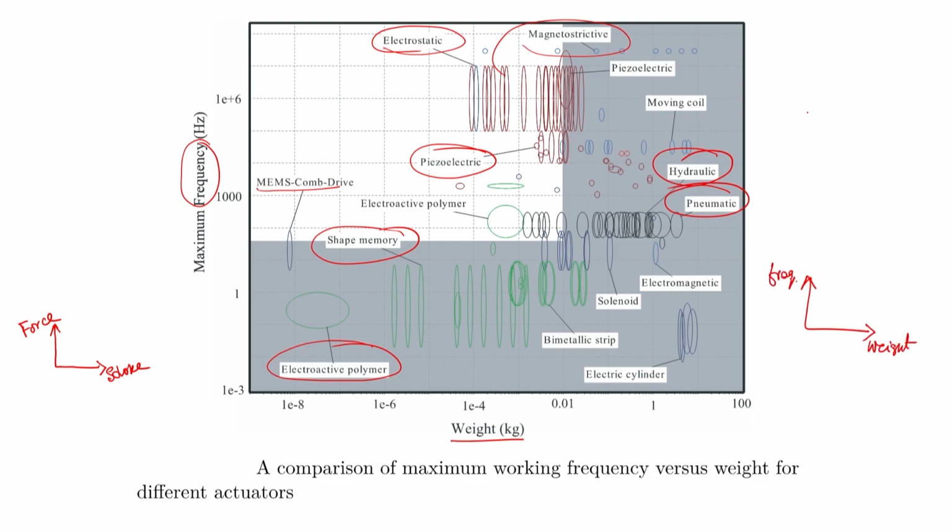Okay. Of course, you can have situations where you will be choosing the actuators based on force versus weight, how much force I am getting versus how much weight I am getting, or the other one, how much stroke I am getting versus how much weight.